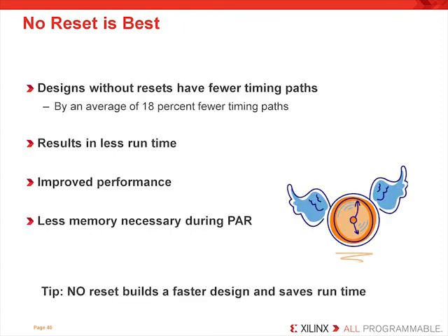Meeting your timing objectives is a lot easier when your design does not have a global reset outside of the GSR. In fact, performance improves by an average of 18% compared to designs that do have an additional global reset. Now, this also speeds implementation time and requires less memory during implementation. So maybe instead of saying no resets, we should just say, be sure you use the GSR.